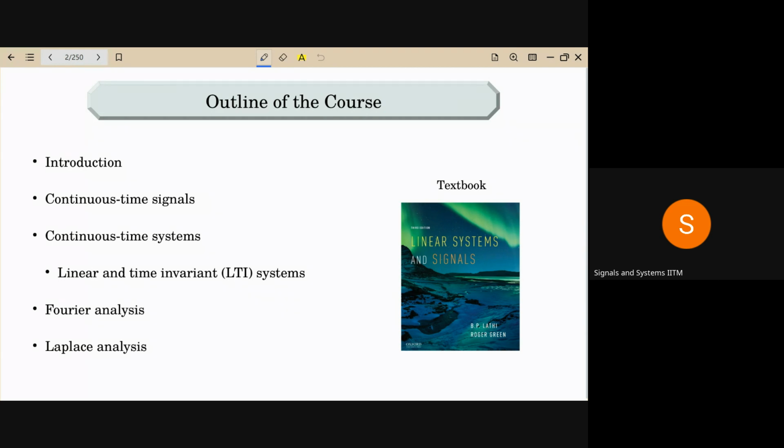Fourier series you can directly compute from whatever we have studied, but for Fourier transform, slightly more information is required to compute it in simulation than what we have studied, because we have studied only continuous time, and we can never simulate a continuous time system on any computer. We can simulate only discrete time systems. So that connection is still not discussed in the course. Maybe in digital signal processing it will be discussed. For now, you can just use the inbuilt function to compute the Fourier transform.